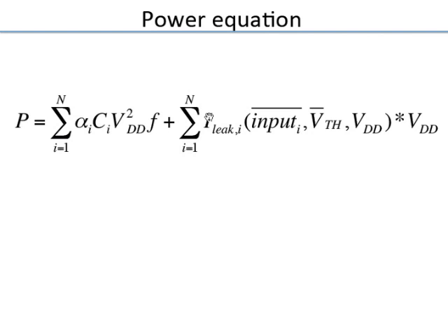So this you again sum over all the gates. As we said, N in typical chips will be in the millions, so very large numbers. So this kind of analysis has to be done through automated tools. That is where in digital design, whatever techniques you come up with for analysis have to be incorporated in the design tools.